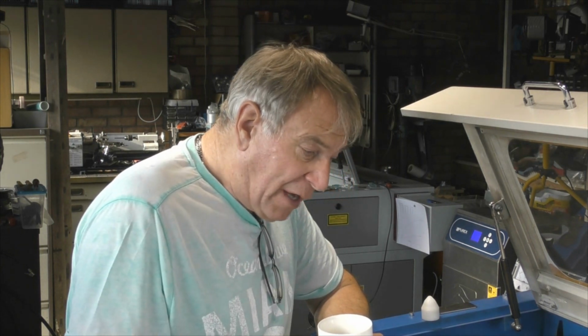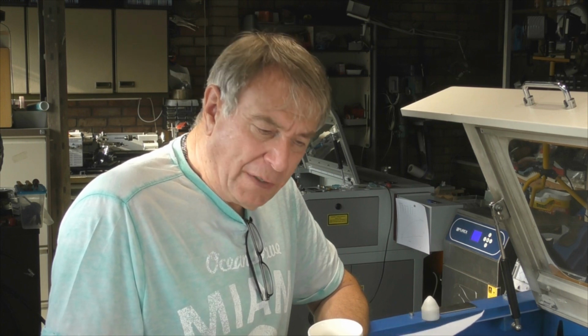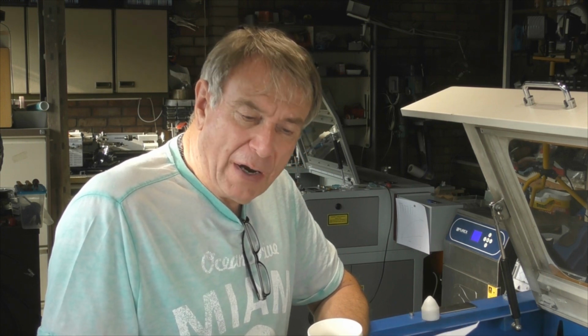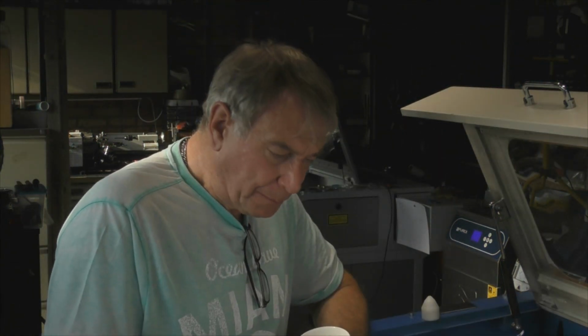Now, the first thing that I've got to do is to look at my calibration graph and decide how we're going to use that in future. Because, to be honest, using 70 watts is just totally unacceptable. As with most engraving, you only need a small amount of power. Well, we are doing some digging, some cutting. We're burning away. So we do need some power. I don't think we need anywhere near the 68% power, 72 watts, that I was throwing at this job.